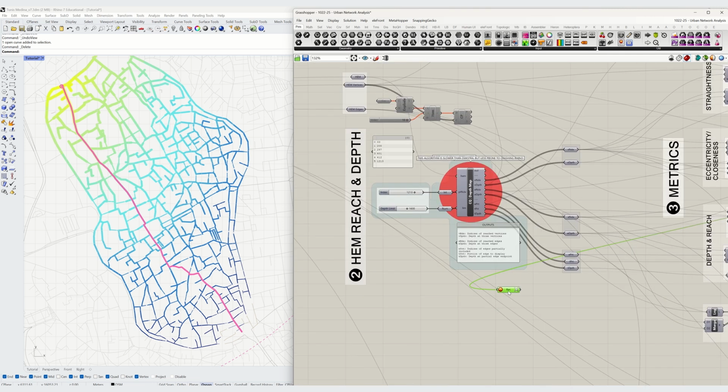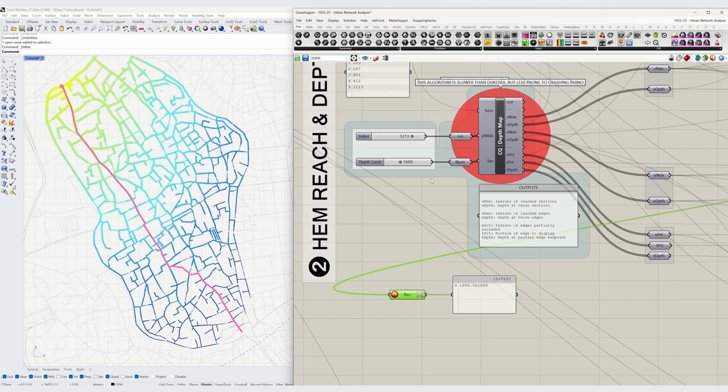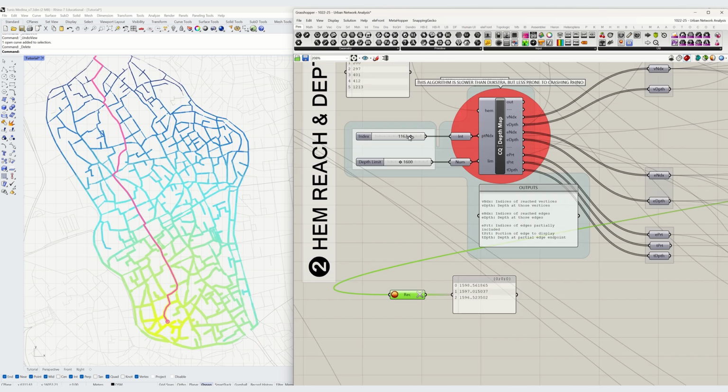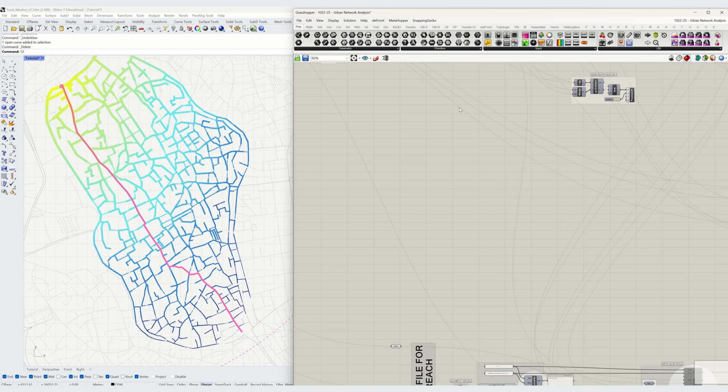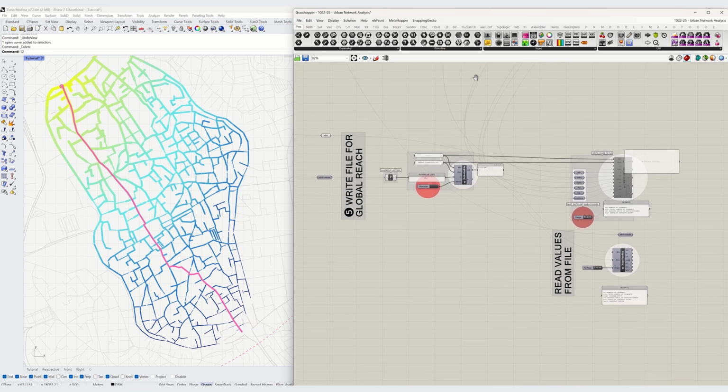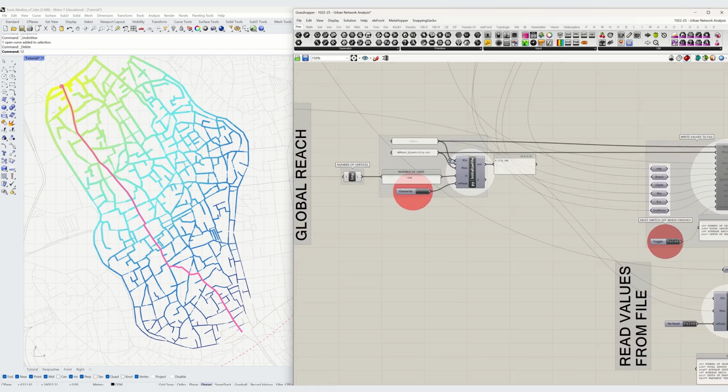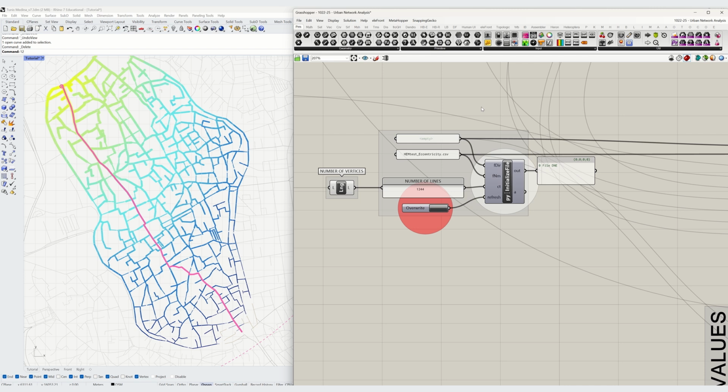Saving the values could be done with Grasshopper's data recorder component, but this is not ideal for such a large set. Instead, this script will write the data into an external CSV text file that can then be reopened at any later date without having to recalculate everything.